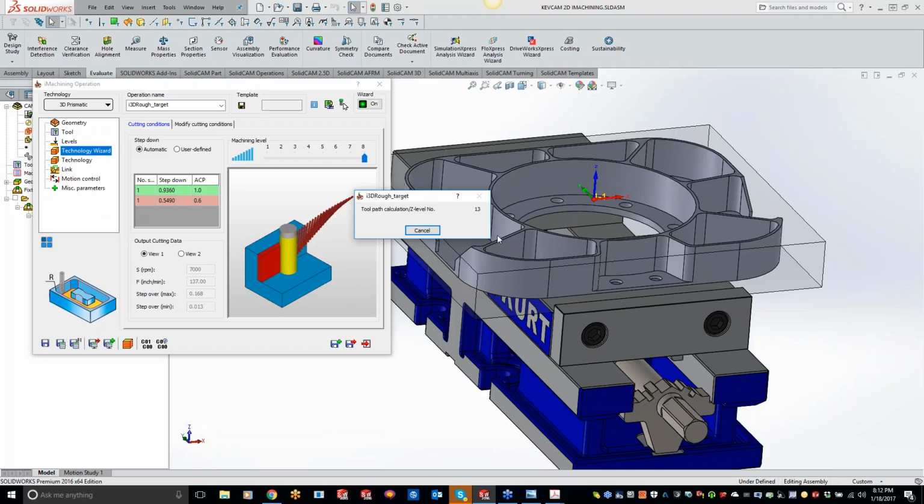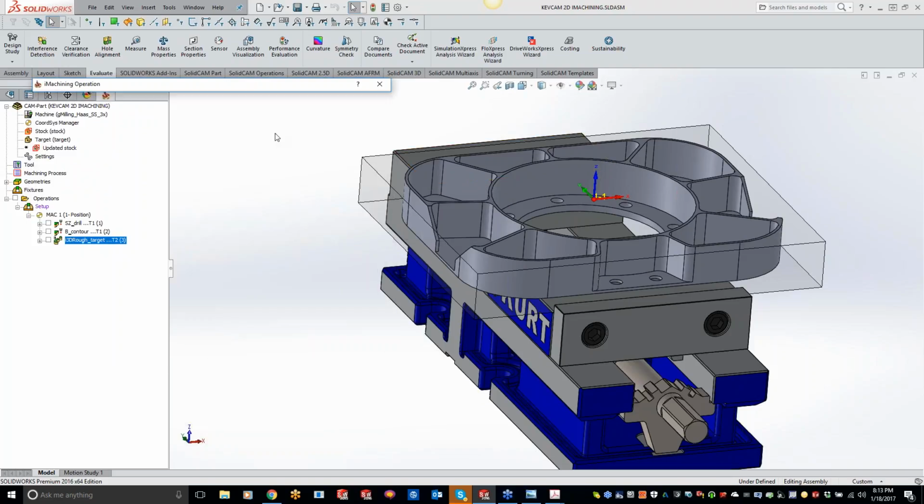Kevin, that's a really good point. In a traditional pocketing toolpath, where the cutter goes into the corner, you always hear that familiar squeak, and then that chatter or wavy pattern that you see in the corner.